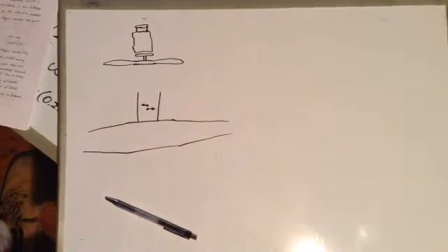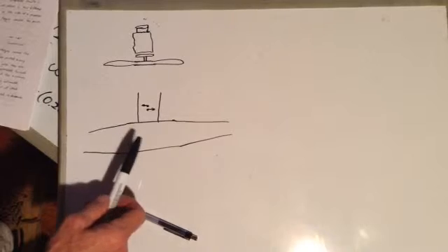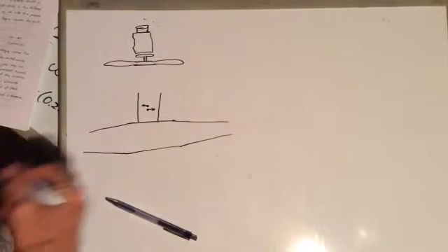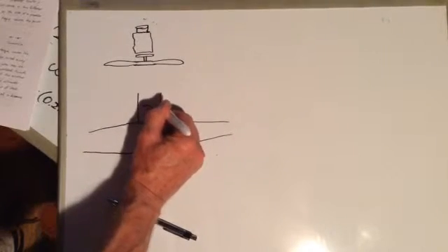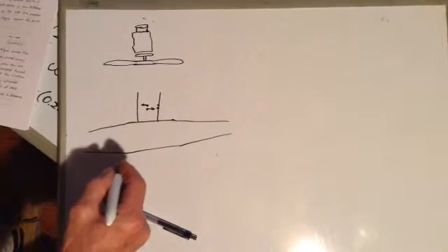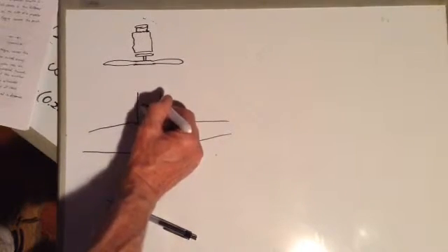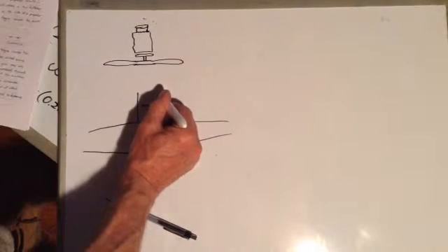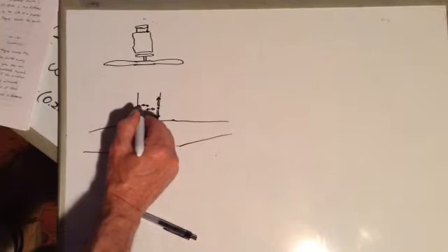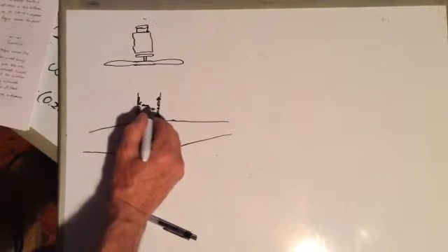The lesson to be learned here is that this propeller shaft is subjected to two different types of stress in two different directions. Let's look at the two points on the side of the propeller shaft. Okay, these two, let's draw them over here. So when this side is in tension, whatever's on this side is always in tension. So this point is trying to pull away from this point. They're being pulled apart. When these two points are on this side of the propeller shaft, they're being compressed together, but yet they're still being sheared the whole time.